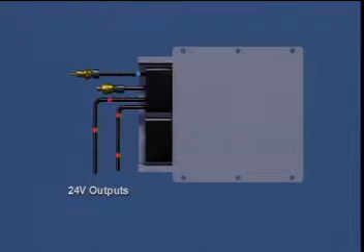The dual outputs based on sensed parameters feature allows for two separate and independent 24-volt outputs to be turned off and on based on input values from 13 specified parameters. These outputs could be used to activate devices such as a fan clutch, audible alarm, or lamps.